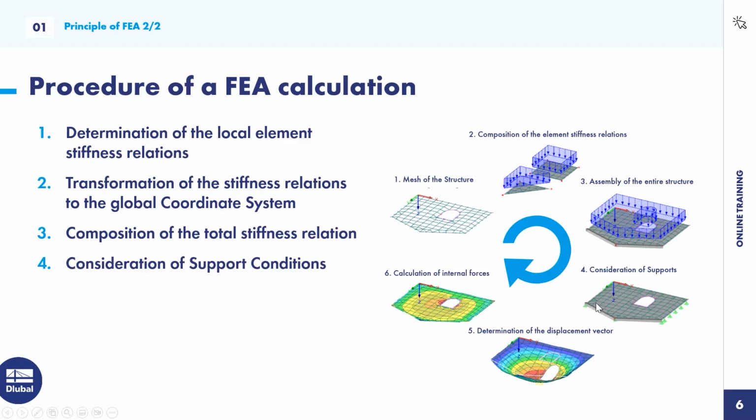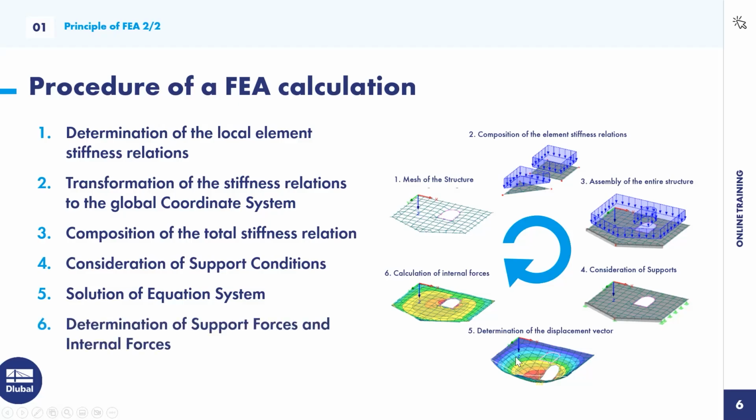And when everything is set, we can just solve this equation system. And that's done right here within our step 5. We will solve the equation system and get our displacement vector. And with that displacement vector, we can finally recalculate our internal forces. So that's the whole process.